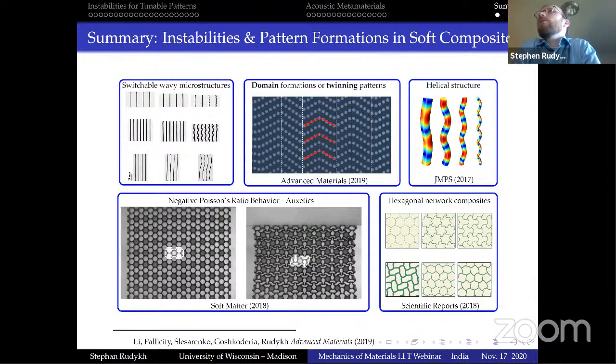You can monitor energies. You can basically do all the analysis by changing the initial imperfections and their amplitudes, and see where you start to get different patterns because of that. Because you don't want to artificially induce something that the system doesn't want to develop. So we use different types of disturbances there, including some random ones, to get to the bottom of things.